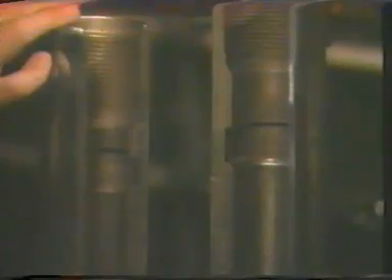The landing nipple is machined with an internal profile to provide a place for a locking mandrel to lock into the nipple to anchor a subsurface control, as shown in these cutaway nipples. The nipple is also machined with a polished area below the locking profile, which is called the packing bore. The packing bore provides a smooth surface on which the seals of the locking mandrel can seal for pressure control in the well bore.